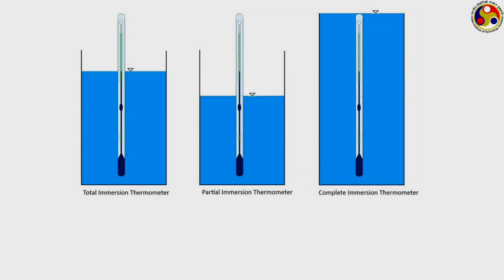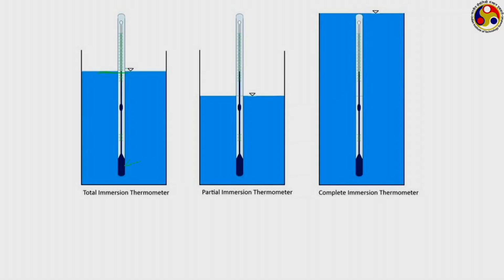So, only the meniscus should be just slightly above the container or zone where we are measuring the temperature, but the entire bulb and the liquid column should be exposed to the temperature which we want to measure. This is probably the most advantageous kind of thermometer, the most accurate option that we can have, but one problem is, how can we know how much we should immerse? That will only come after getting the temperature measurement and maybe going through a few trial and error.